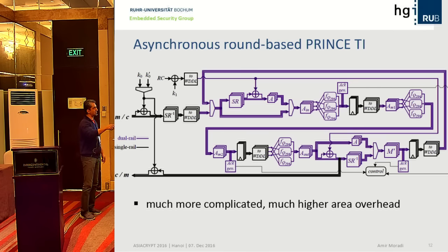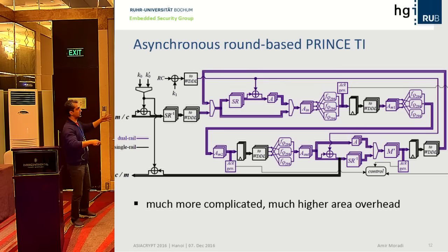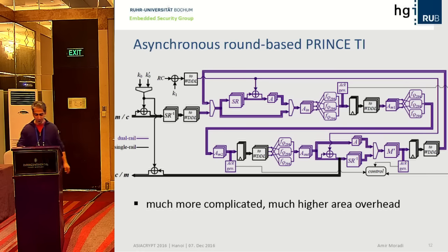Then you have to put in the registers, but the point is you can have another part of the circuit which triggers these registers. It means it's completely independent of the clock, but when the computation is done here, it tells the register to save. And again, for the next part, when the computation is done, it says, okay, save, and so on. Then this circuit needs only one signal to say start, and when it's done, based on the control logic, it gives you a done signal, without any external clock.